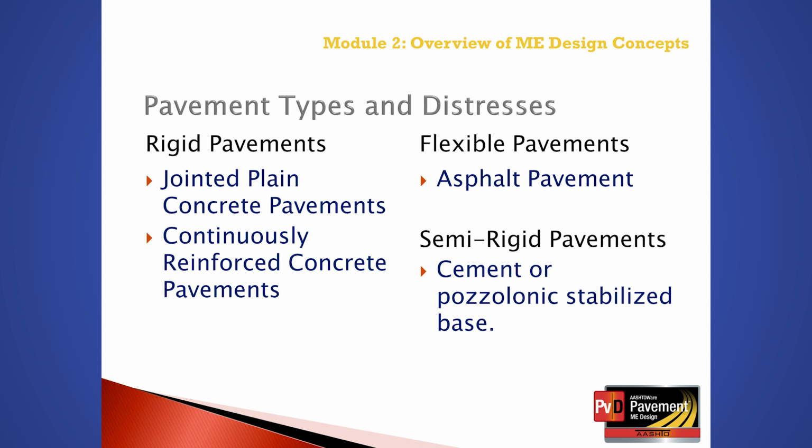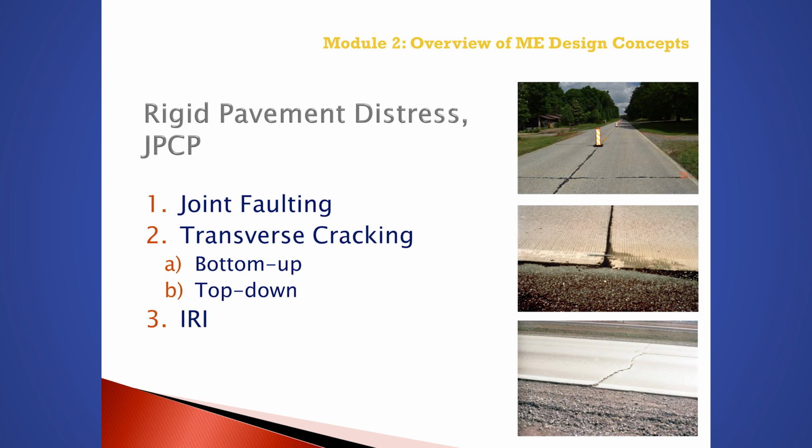In addition, semi-rigid pavements consisting of an asphalt surface over a cement or pozzolanic stabilized base is an appropriate design strategy. The next portion of this module will define the different distresses considered for each pavement type or pavement design strategy. The distresses computed using the PMED software for jointed plain concrete pavements are shown on this screen.